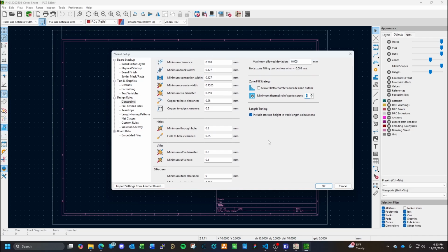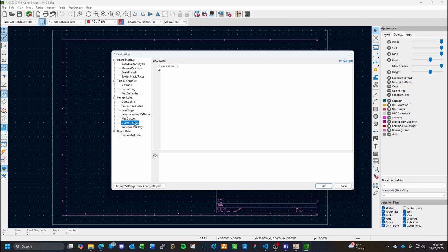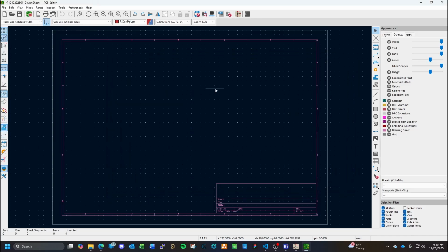So one of the things I was kind of missing, hopefully we can do copper pours on here. I really do. Teardrop, custom rules. I don't know how we can apply. Can we create a rule? Well, we'll have to figure that out. Okay. Go and save it. All right. So we kind of predefined some of our board parameters, our constraints. That way it'll just make it easier when we start running things.